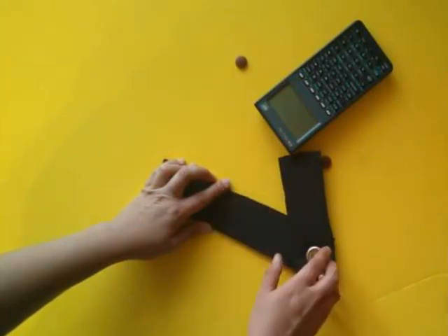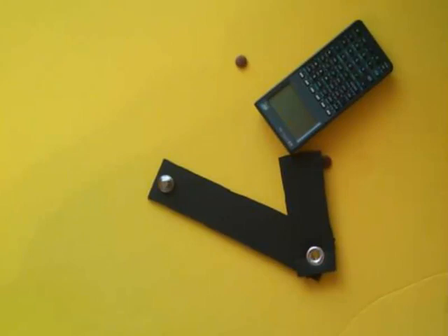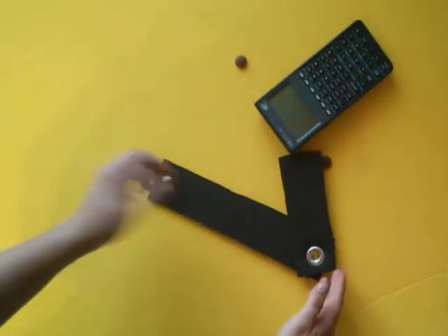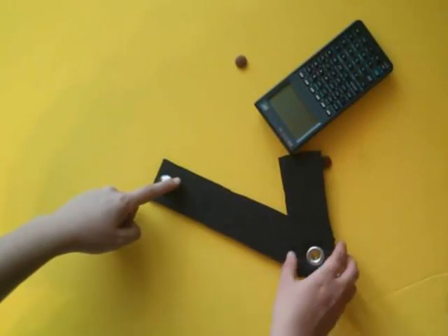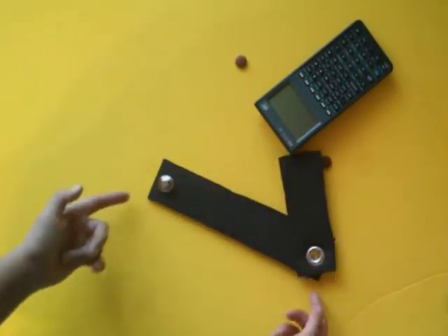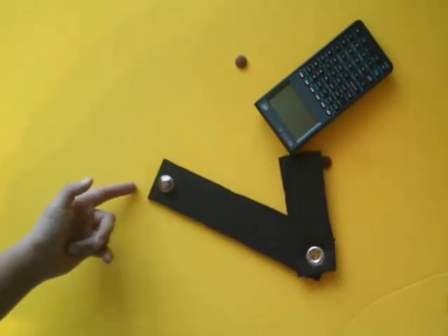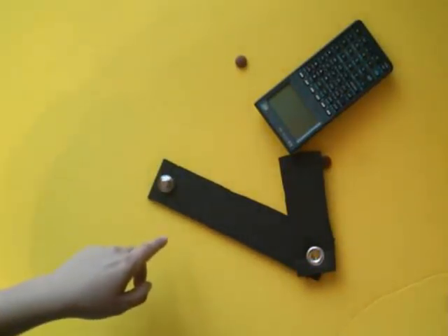And that would happen approximately as I've shown here. I'm going to take note of what is the theta 1 angle at which the second link first makes contact with the obstacle. This angle is approximately 330 degrees.